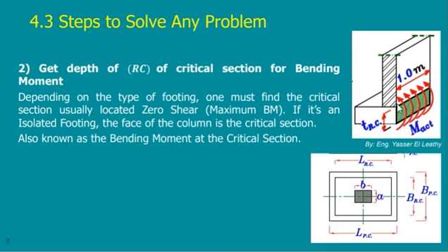So I assume I have a section here, calculate the moment, the actual moment acting on my footing. I take this moment and use it in my design.